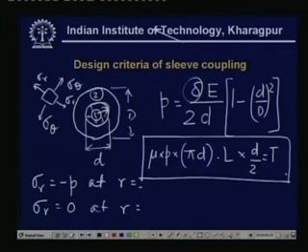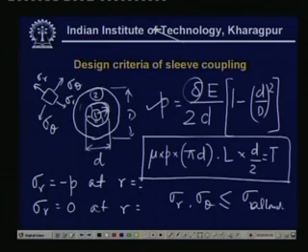Of course, from here we can find out various things, that is, we can find out the bursting pressure inside, sigma theta and sigma r etc., knowing this P and knowing Lame's equations, and this sigma r and sigma theta must be less than some limiting value or allowable value. Now let us come to the situation where